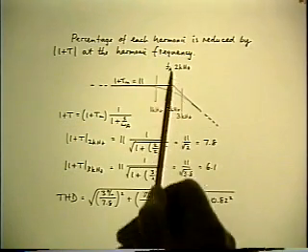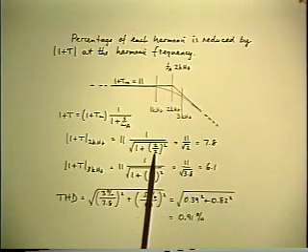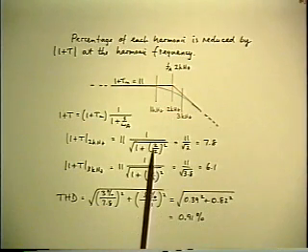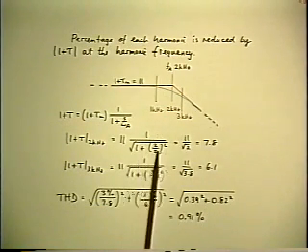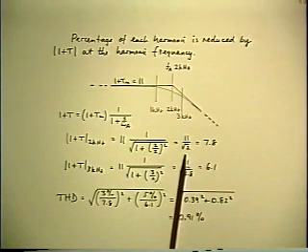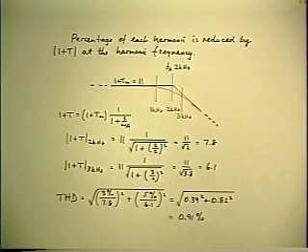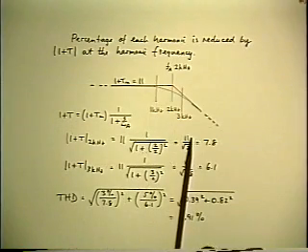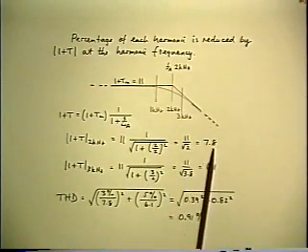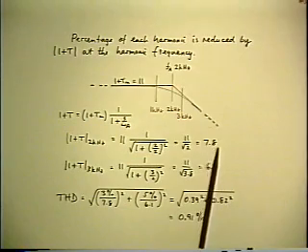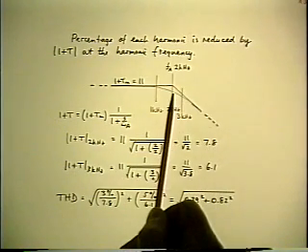And that happens to be the same as the corner frequency. So the result is 1 over the root of 1 plus 1, or 1 over root 2, which is the 3 dB down point, of course. So the flat value is 11. Divide that by root 2, and the answer is 7.8. So that's the magnitude of F at the second harmonic frequency.